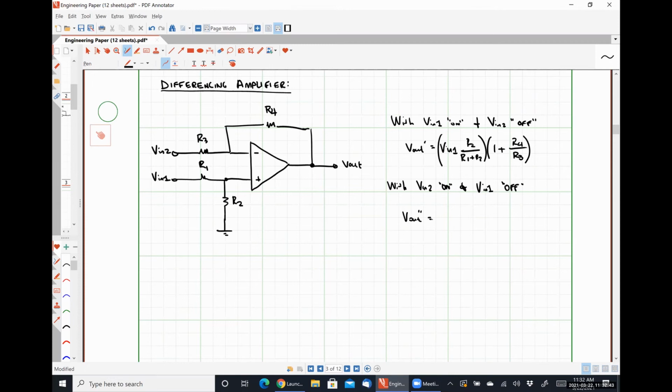So we have this resistor R1 placed between this node and ground, and this resistor R2 placed between this node and ground. So R1 and R2 are in parallel, so they just look like some equivalent resistance, right? But they're connected directly to the non-inverting input terminal. How much current can flow through them? 0. So the voltage drop applied at this node has to be 0.